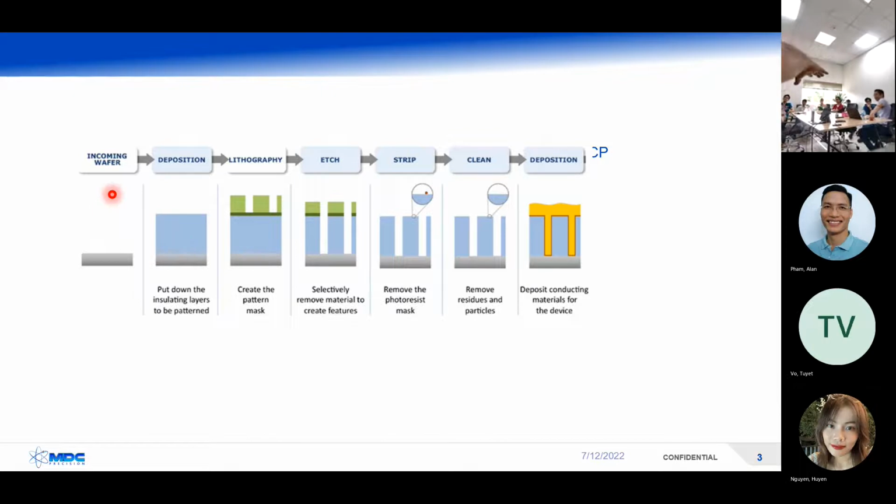Am I going way too fast? It'll hopefully come together a little bit, but I want you to understand that what Lam and Applied do is really a gas chemical mix that we put a wafer into to either etch away or push the film down. Okay? So now, once I've cleaned it all off, you notice how we talk about residue and particles, right? So then it has to go through a clean cycle. If our gas line had little bits of free metal in it and those come out and are on here, they need to get cleaned off or they can cause a problem, okay?